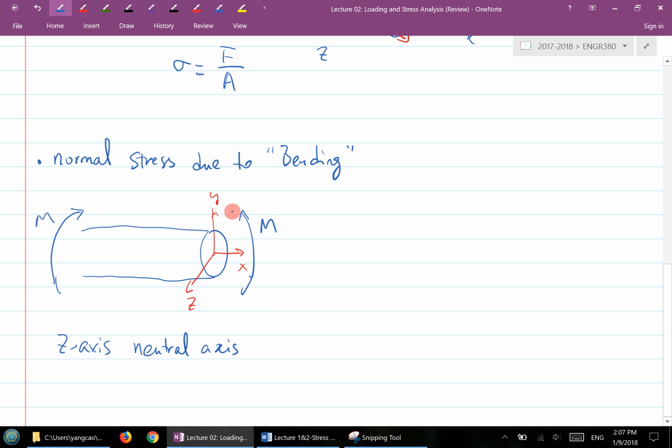But say in your statics, when you want to know what is a positive moment and a negative moment, how do you define that? Clockwise or counterclockwise. Counterclockwise is considered positive. So that's one positivity or negativity. What is considered negative there is different when it comes to drawing the bending moment diagram. When it bends this way, it's a positive bending moment, and when it bends this way, it's a negative bending moment. I want you to be aware that there are different positive and negative conventions here.